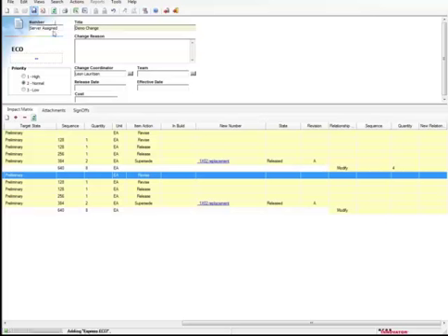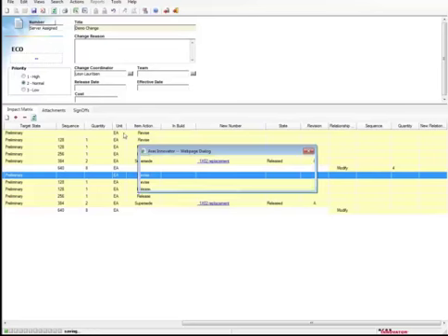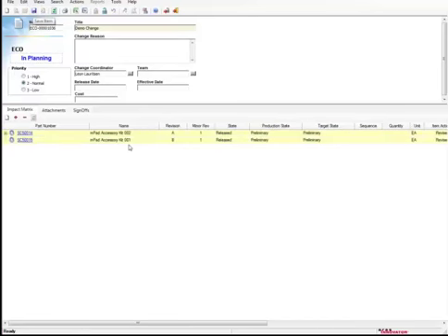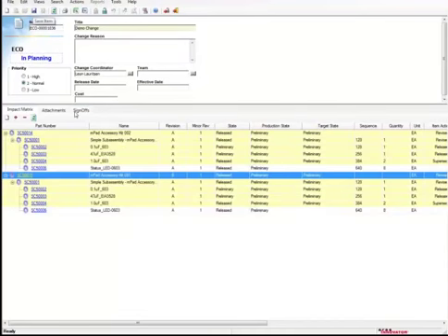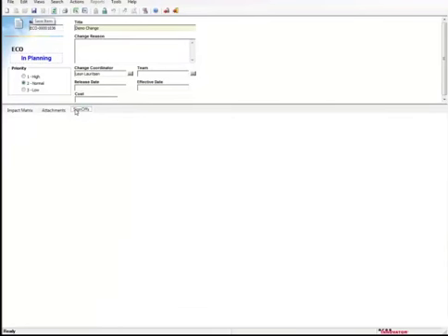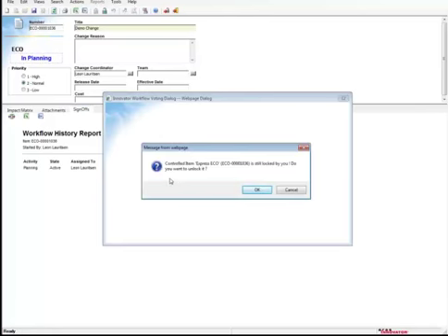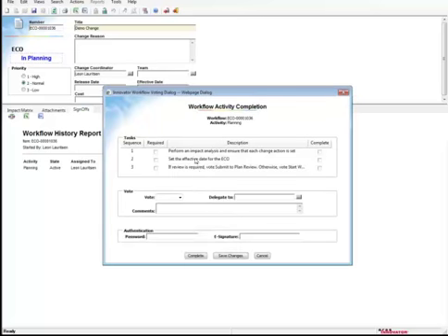As a change agent, I've now illustrated all the things that we're going to do as a part of it. So the next thing that I need to do is that I now need to route it through my process. So I go to the sign off tab and state that I've now done my work, please send it out into the change process. It states to me that it is locked, so if other people are to work on it, I need to unlock it. So I'm okay with it being unlocked.